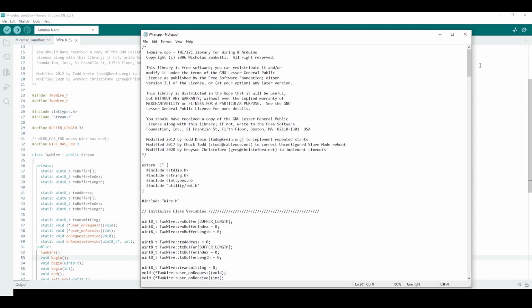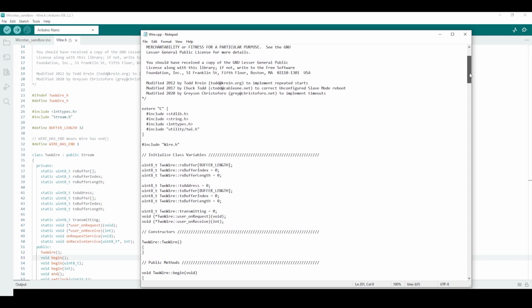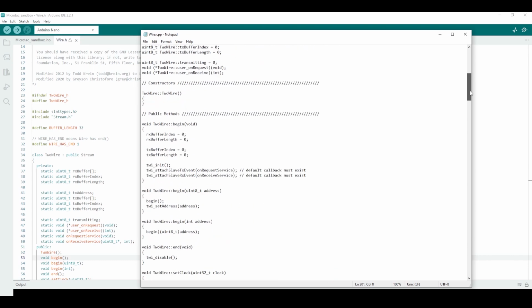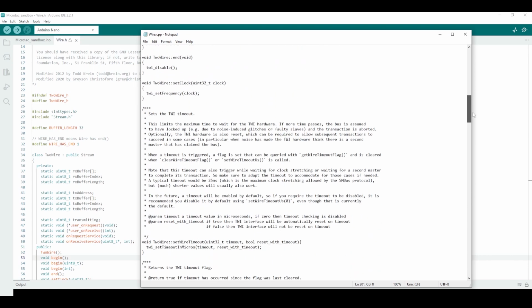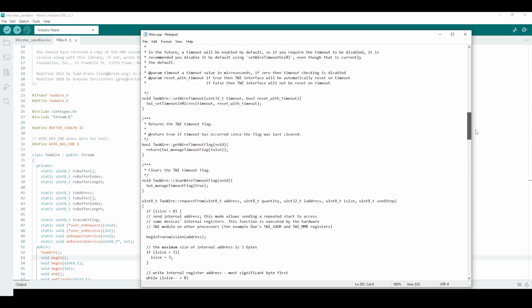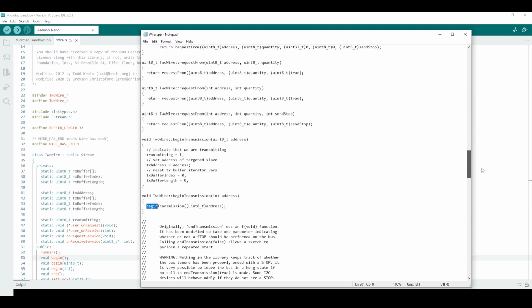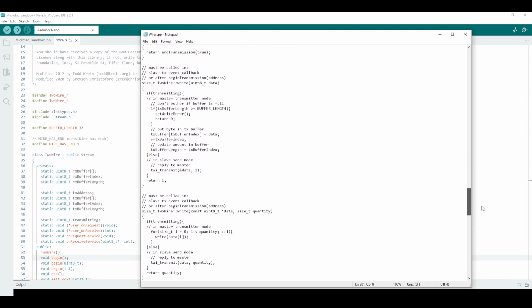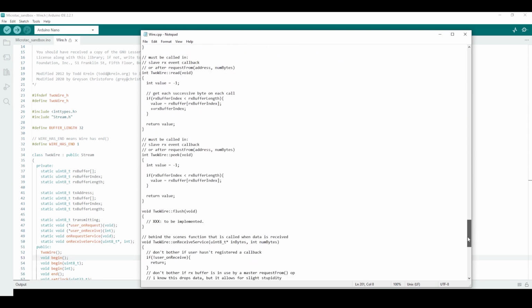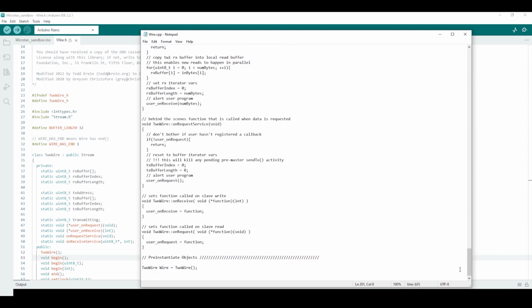And both of those interfaces are pretty easy to implement in software, but I found out pretty quickly that the execution cycle overhead, especially for the I2C bus, is a lot more than I expected. I was really struggling to get even a basic program to work at any frequency above about 8 kHz, which gave me concerns about having enough bandwidth.